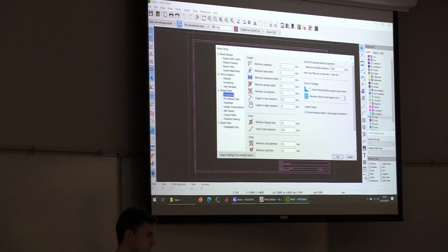We call that our annular width, the width of that sort of donut, that circle. So KiCad's really nice. It's got the icon to show you what that measurement represents. And that's sort of just the width there of the inner and outer diameter of that circle. And then, of course, you have your minimum via diameter, the smallest diameter of that ring.